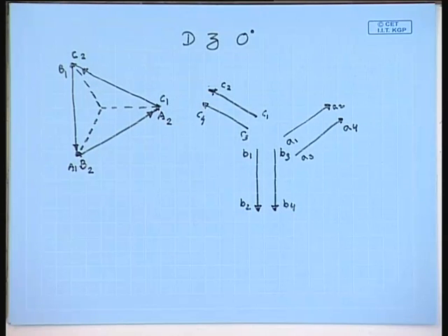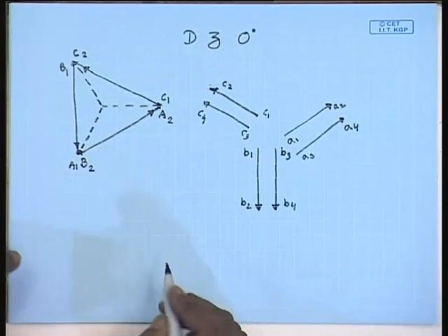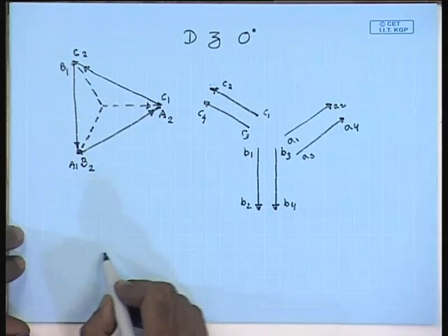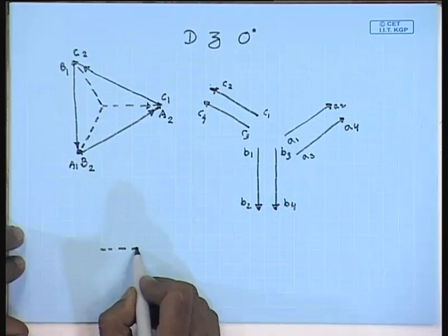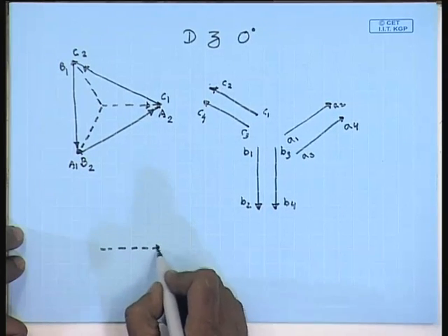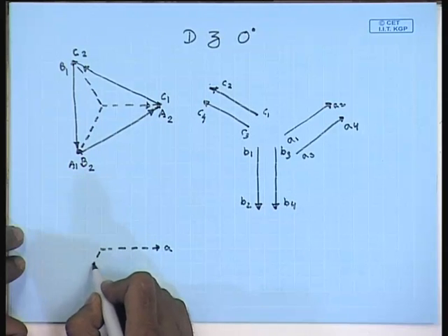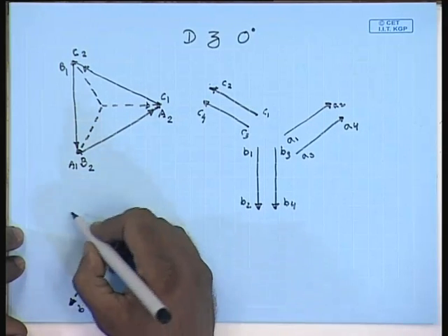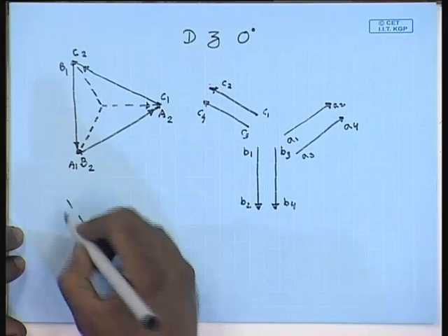It is necessary to make the connection as Dz0, which means that the zigzag side line to neutral voltage should be in phase with the line to neutral voltage of the delta side. Therefore, the zigzag side line to neutral voltage should be, this should be A, this should be B and this should be C.